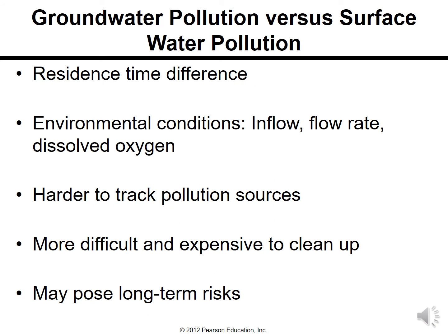Groundwater pollution versus surface water pollution. Residence time is different. If you think about surface water versus groundwater, groundwater has a higher residence time. Then environmental conditions like inflow, flow rate, and dissolved oxygen. If you compare surface water versus groundwater, the dissolved oxygen in groundwater is less, because surface water is always in contact with the atmosphere, where you have oxygen involved.